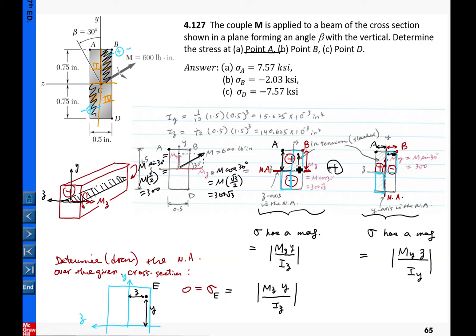In this first quadrant, this is tensile. Now we superpose subsystem 2. For subsystem 2, we have the magnitude MY. Again, E is the point here, and that is the distance from the point to this neutral axis, which is the Z coordinate here. We copy this from here. In this subsystem, where E is located is compressive. We ask that this sum equal 0.